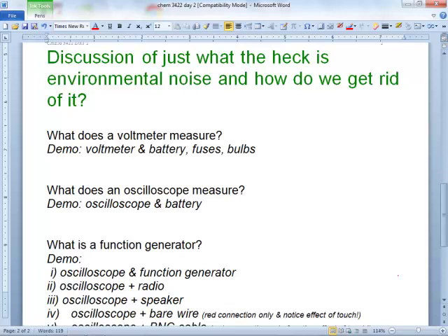All right, red goes to positive, black goes to negative. All right, hold that up, Sandy. You can hold that voltmeter up so people can see, and the voltage is 9.2. They give you a little extra on these new batteries, right? So that way they can make the expiration date 20 years from now instead of 5. Okay, so that's good. What if I would switch these probes around and connect the black to positive and the red to negative? What happens to this guy? Yeah, it just reads the opposite, hopefully. Okay, so what else can you do with a voltmeter?